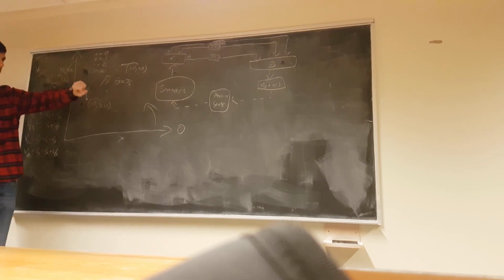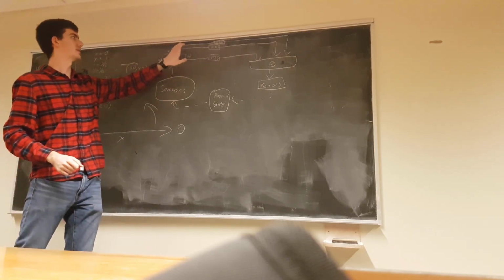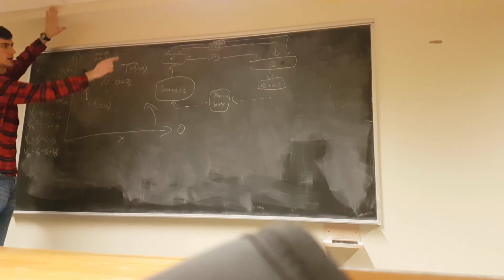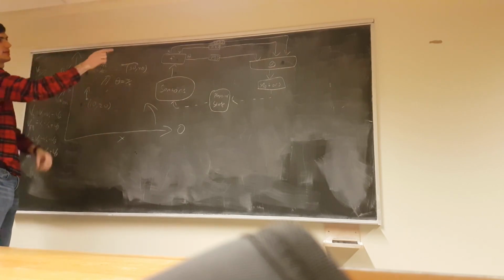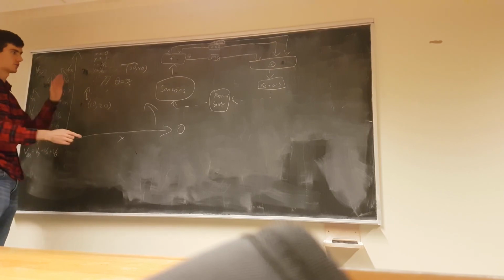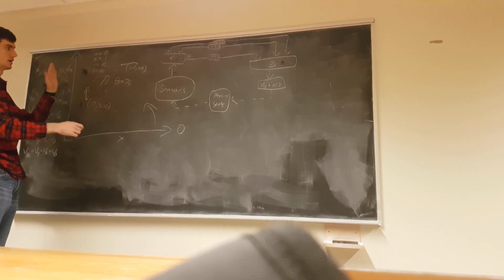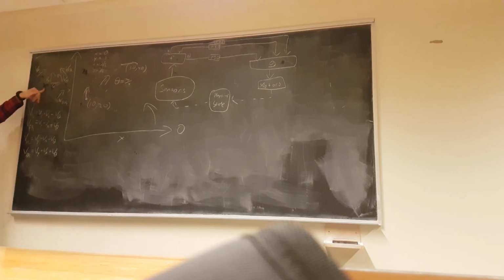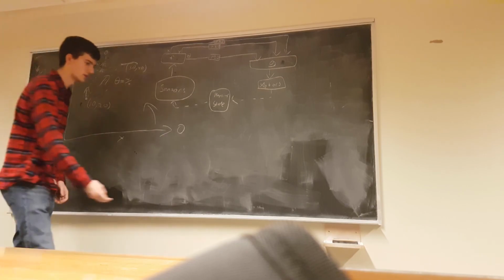So, to recap, we take the movement in what we call global x and y, that our PID gives us. We rotate that by the current orientation of the robot to get what we would call local X and Y. And we put that through this linear transformation to get actual motor voltages. And then as a final step, we make sure that none of them are going to get capped down. So if the largest one is greater than 1, we scale them all down. Make sense? Cool. And I believe that's as far as I want to go.